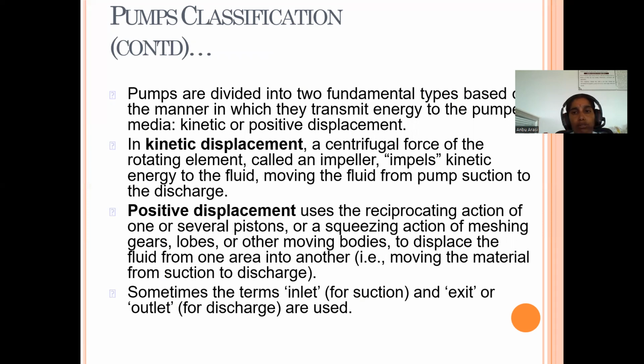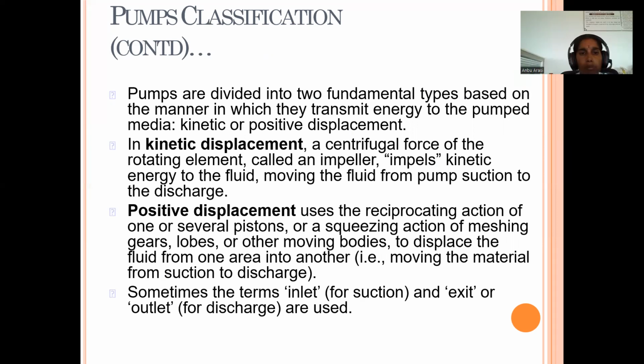Pumps are divided into two fundamental types based on the manner in which they transmit energy to the pumped media: kinetic or positive displacement. In kinetic displacement, the centrifugal force of the rotating element, called an impeller, imparts kinetic energy to the fluid, moving the fluid from pump suction to discharge.